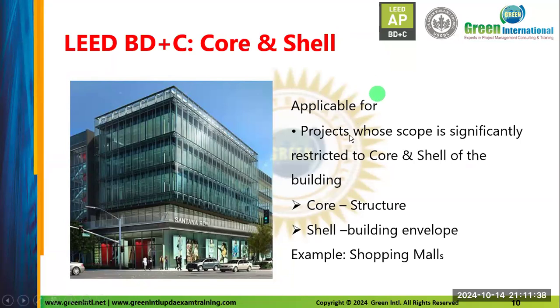This is the only case. Why? You did not finish the building. You put the envelope, yes, nice aluminum cladding with glazing, but inside there is nothing. There is only concrete and major air ducts and machines equipment. I don't put any tiles, floor tiles, wall tiles, ceiling panels or anything. I don't put the lights, the lamps, and so on. So this is Core and Shell.